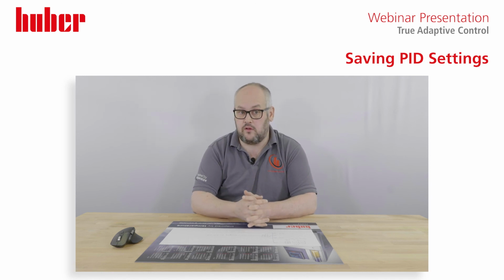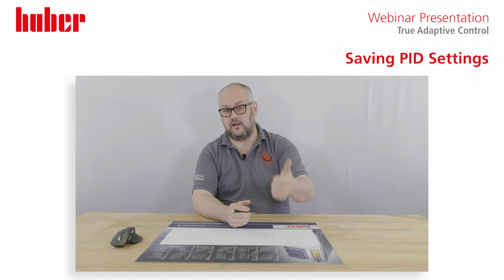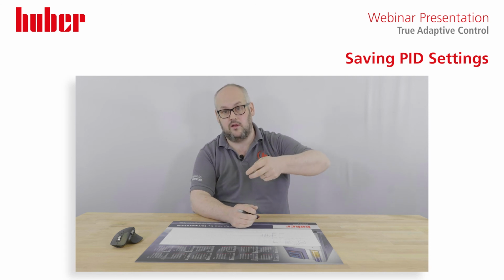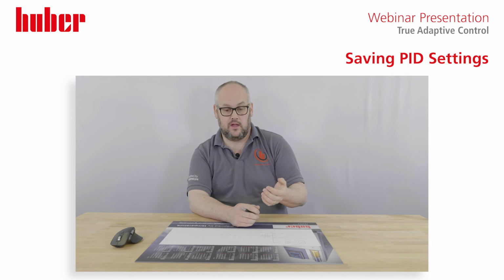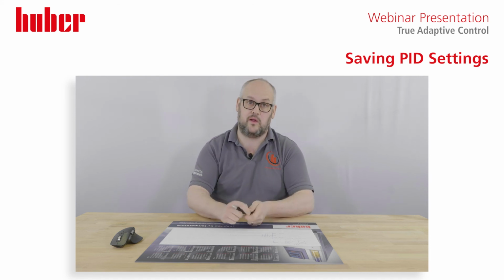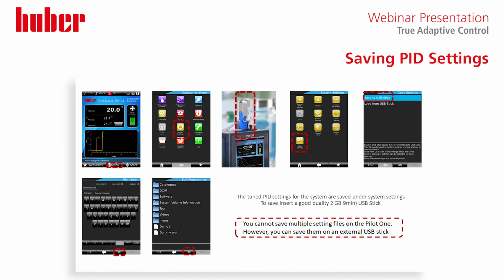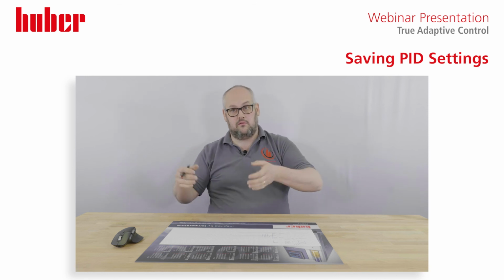Hubers are often used as a utility machine, and I'm aware of many cases where, let's take for example, a 510W is used on a 20 litre glass reactor, a 100-litre steel reactor, and a 200-litre glass-lined stainless steel reactor. They will all have different tuning configurations. How we get around this is, if you insert a USB stick into the top of your Pilot 1, you can then go Menu, System, System Settings, and you can actually upload the global system settings onto that USB stick. And you can then name it.